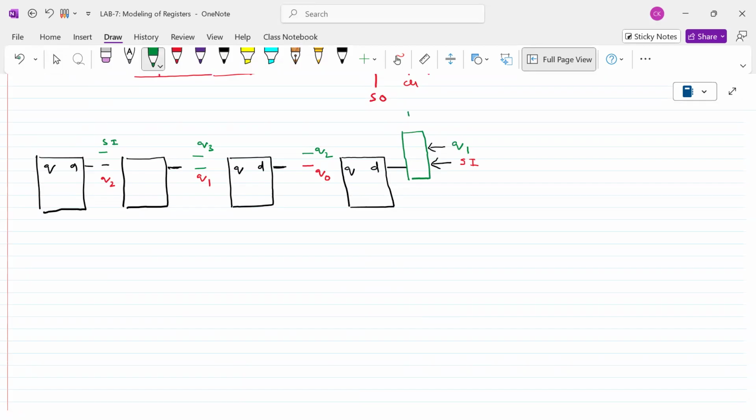We use one enable signal. If enable signal is equal to 0, what is happening here? Let us assume that this is the first line, this is the second one. What should this be, shift left or shift right? Shift right. Let us assume Q1 will come here. The first one is Q1, Q2, Q3, and serial. If it is coming from there, what kind of shift is it? Right shift operation. If enable is equal to 1, for example, then what does it have to do? Shift left operation. Therefore, we can simply write one multiplexer here.